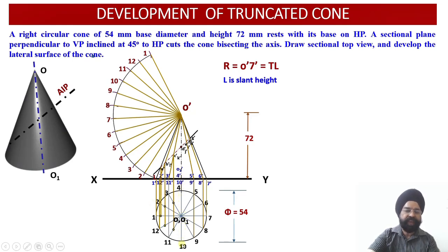The same thing we had discussed while we were discussing the projections of solids as well as the section of solids. So what we have to do, if we cannot see through this, because these 2 points were overlapping on the axis? Rather than looking from this side, we have to go 90 degrees and look from this side. The moment we start looking from this side, these 2 points will be visible to us on the outermost boundary. Whereas from the other side, even though they were lying on the outermost boundary, they were coinciding with the axis point. So once I bring D' and J' down, no point of intersection is obtained.